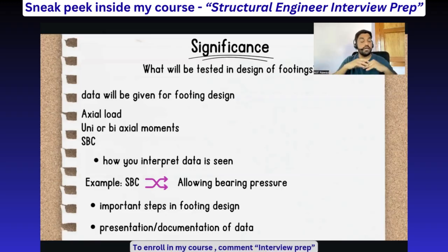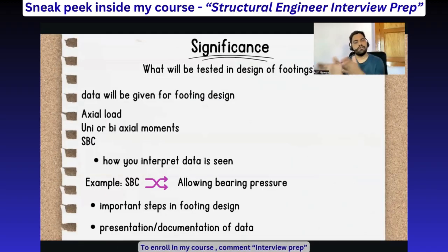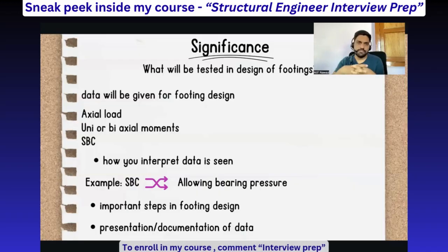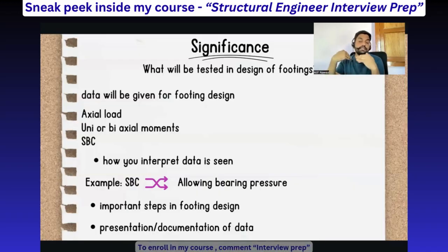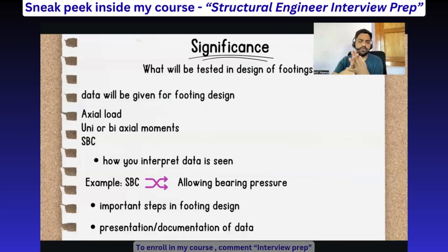First is we find the area of footing. We know the SBC, we know the load. So first we find the area of footing required. Then what we check? The base pressures. So we have stipulations for maximum and minimum pressures, so that we need to specify. After that, there is finding the depth with one-way shear and two-way shear criteria. What is the depth we fix? And then AST and other things, minimum steel and all those checks.